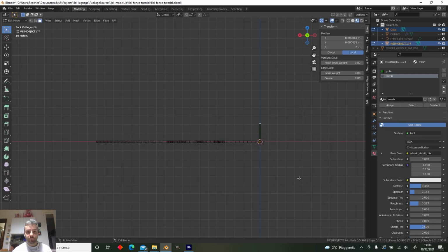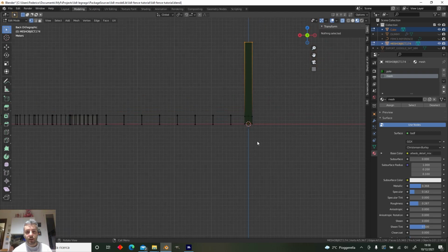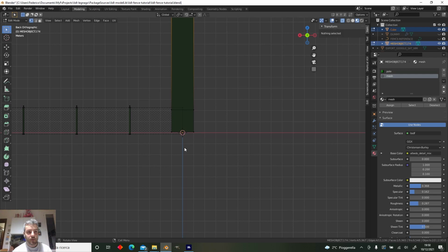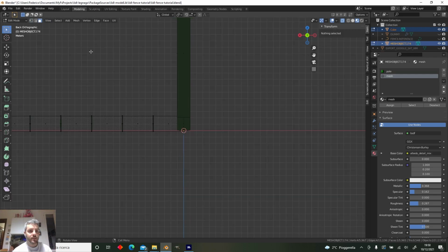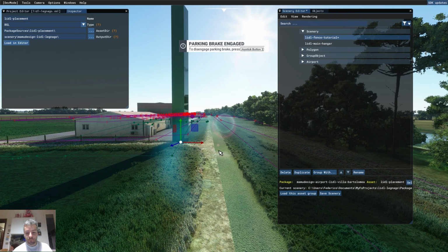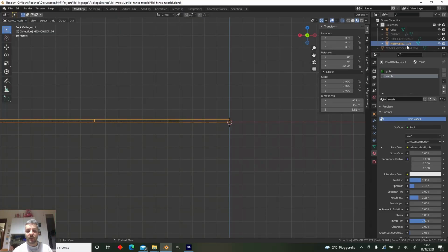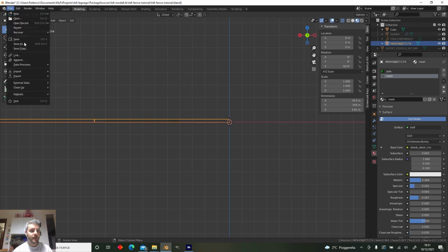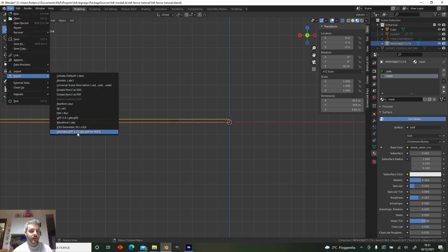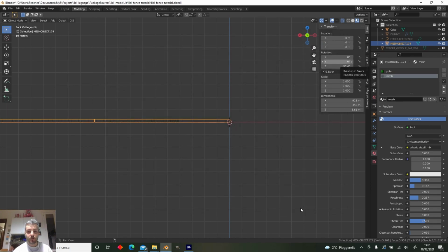With the sim open in Blender, I don't need the big cube anymore, so I'm gonna delete this. And now we can export. So let's open the console, clear everything. And now we can export this in Blender. File, export, Extended glTF, fence tutorial, export.